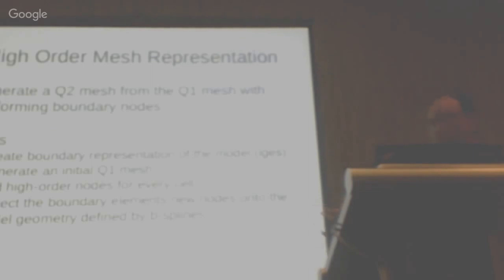So there are several approaches to tackle the problem of how to get a quadratic mesh over a general geometry. Our approach in this work was to start with a linear mesh representation, using commercial mesh generators or open source ones over your airfoil. Then you make a pre-processing step in your simulation to generate a quadratic mesh based off the linear one. This guarantees that the linear mesh nodes are actually on the geometry, so that's the mesh generation software problem. Our problem now was how to project these middle face nodes onto the actual geometry.